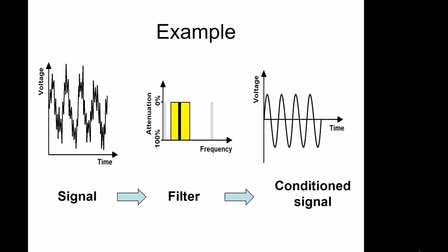So as an example of a filter, this might be our original signal. You can see it's quite noisy. First of all, we've got a DC offset. And in terms of frequency components, it is this here. We've got our signal of interest, which is this gentle undulation. And that is our signal at this point. And then you can see we've got some sharp spikes, which is our high frequency noise. And this is this frequency up here. So we'd like to remove this, and keep this part.